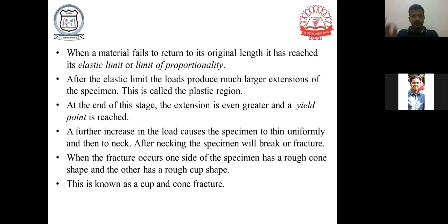Okay, the fracture which usually occurs in a tensile test is usually cup and cone fracture. But if you are using a ductile material, then and only then will you find this cup and cone fracture. This last sentence in this slide you can see over here, cup and cone fracture. Okay, so this cup and cone fracture is usually observed in materials which show some ductility.